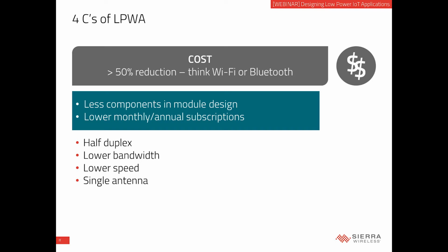Thanks to that as well, because we're using half duplex, we can save on filters, and we can also use what's called software-defined radio, meaning that now these devices can be compatible, with just a software setting, with all the different networks across the world, in North America, in Europe, in Japan, in China, where regular 4G devices always had to be compatible with the frequencies used in specific areas of the world. Now with these technologies, it's another gain that you can deploy them everywhere thanks to this half duplex and software-defined radio.